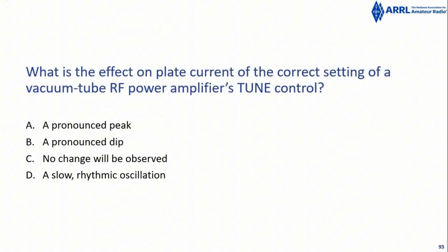Okay. What's the effect on plate current of the correct setting of a vacuum tube RF power amplifier's tune control? You're going to find that dip when you're doing it.